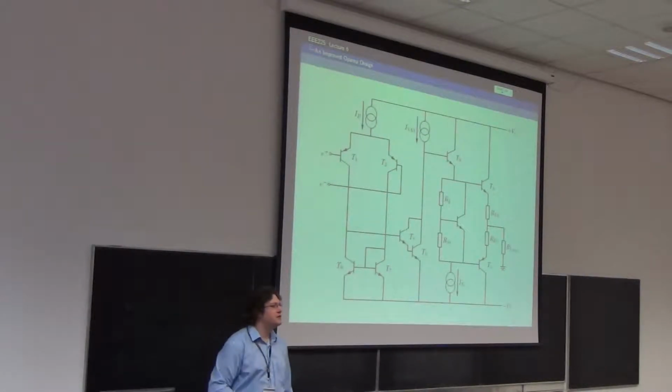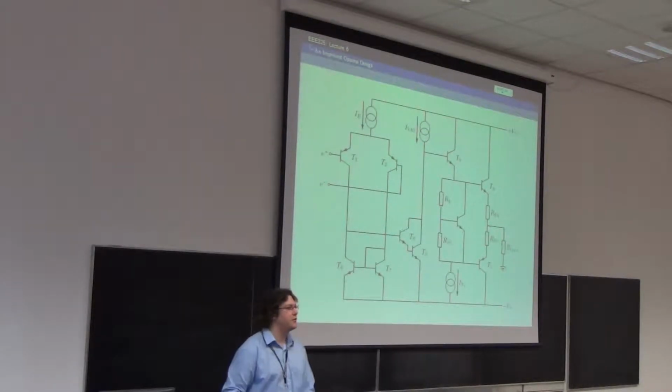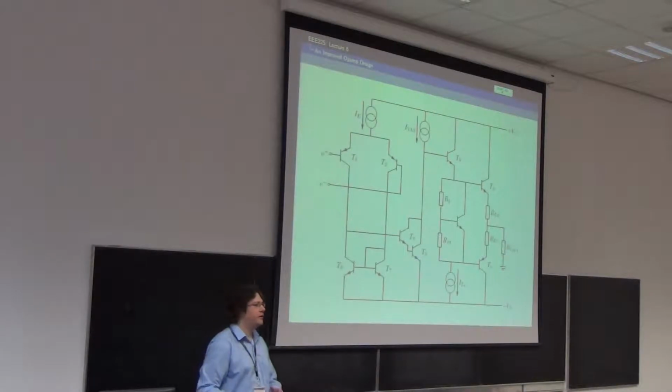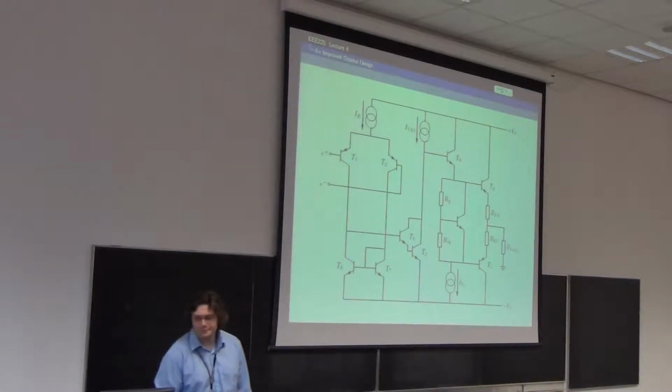So there are reasons you might like to do that, because if you've got some chip-to-chip variation, and you just want the ratio to be right, it doesn't really matter about your variation, it's the ratio that's important. And with individual current sources, you can't manage that.